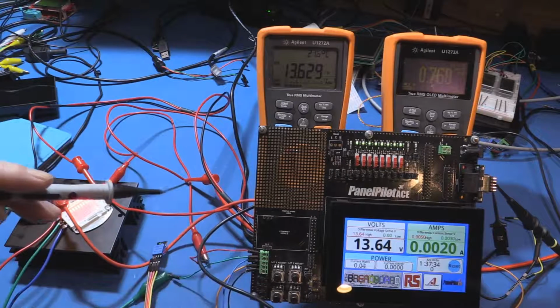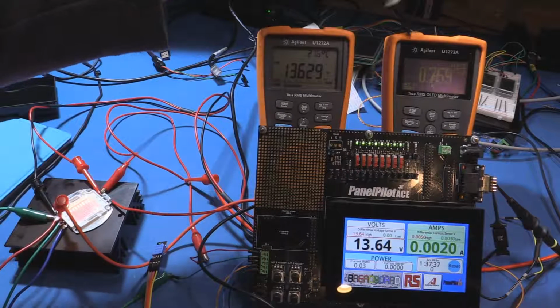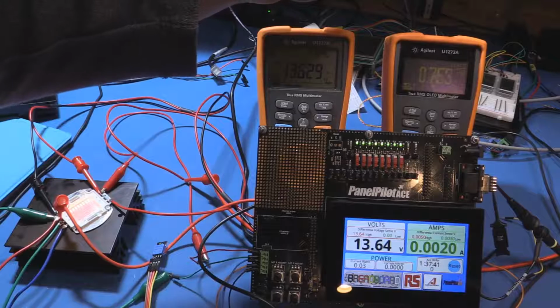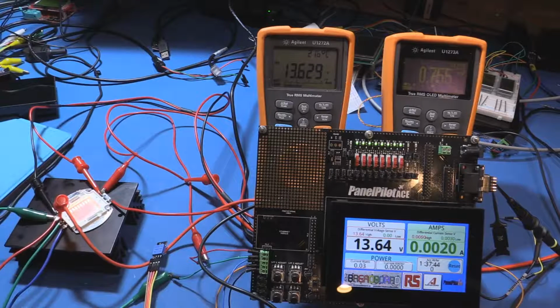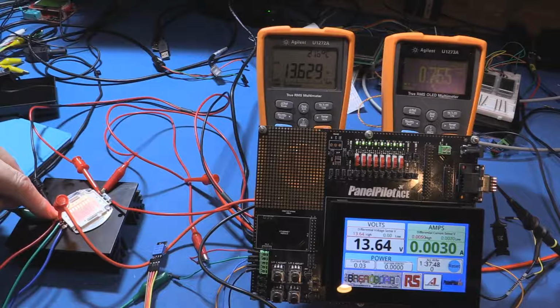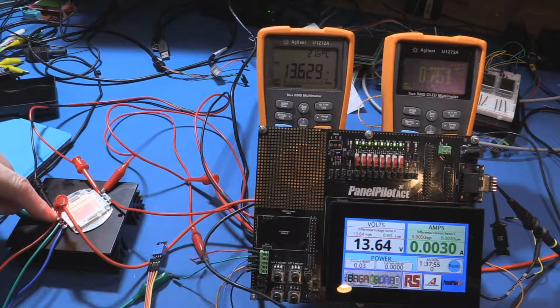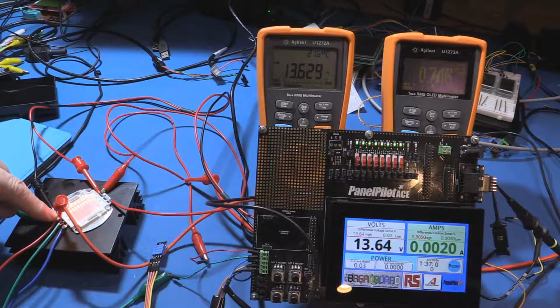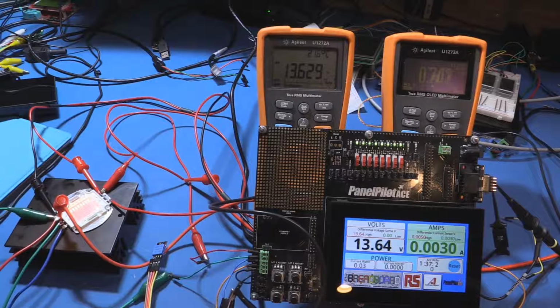Now what I've done is I've got my right hand panel digital multimeter here, the 1273A, measuring the supply voltage on the current. But I'm measuring it, as a lot of newcomers often do, from the LED to the ground terminal down this little ground cluster here, which means that if there are any high currents, the voltage drops across these wires are also going to be included in the measurement, which would offset things slightly.